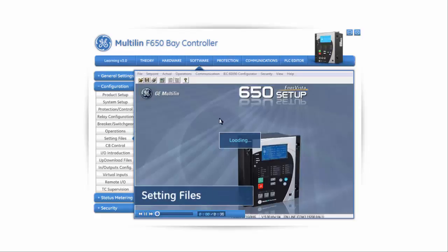The configuration process of a 650 relay involves the use of 2 files. While the files of type or extension 650 contain the complete configuration of the relay, the PEP files are merely a tool to configure the programmable logic that is later integrated to the 650 file. We will pay more attention to the PEP file and graphical logic configuration of the 650 relay further into the training. For now, we will concentrate on the 650 file.